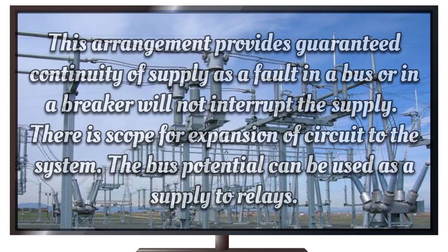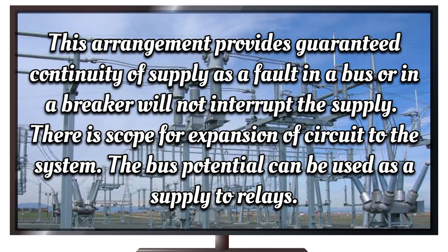Advantages. This arrangement provides guaranteed continuity of supply as a fault in a bus or in a breaker will not interrupt the supply. There is scope for expansion of circuits to the system. The bus potential can be used as a supply to relays.